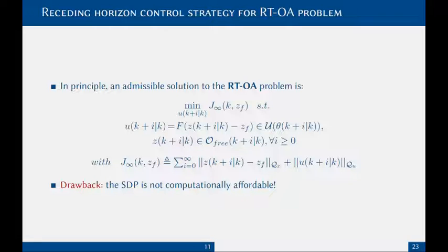The control move at time k plus j must belong to the theta-dependent inputs region, and the j-step ahead state prediction must belong to the obstacle-free region. However, several drawbacks arise in this strategy. In fact, the vision radius r is not infinite, and the feasible input region is not available even for small values of prediction horizon length.